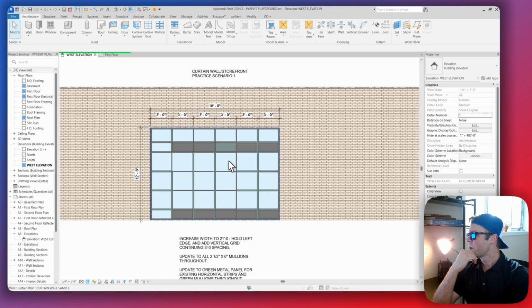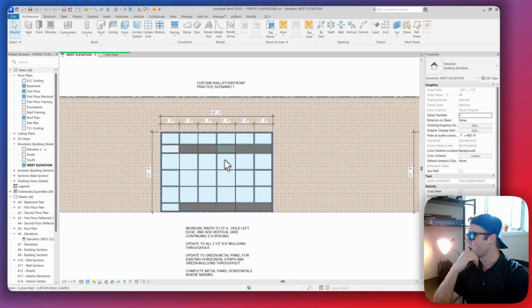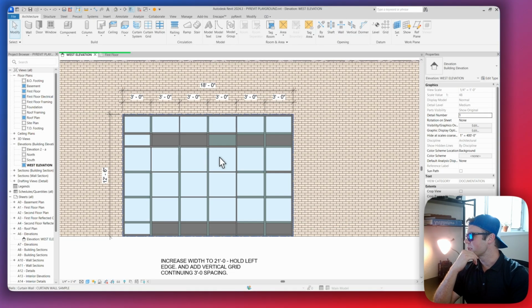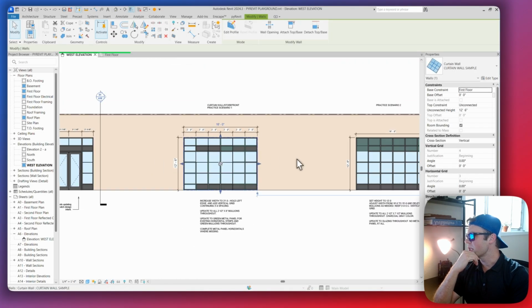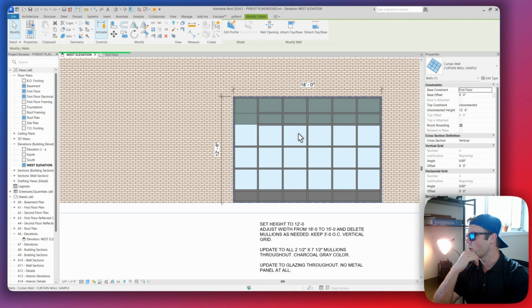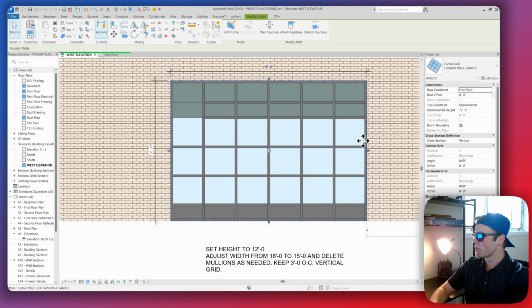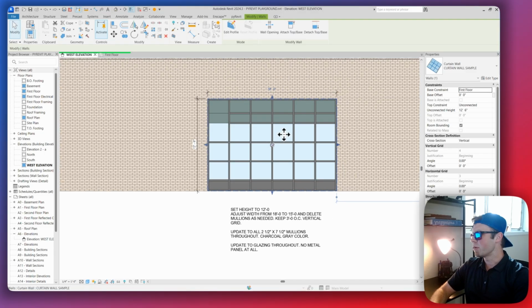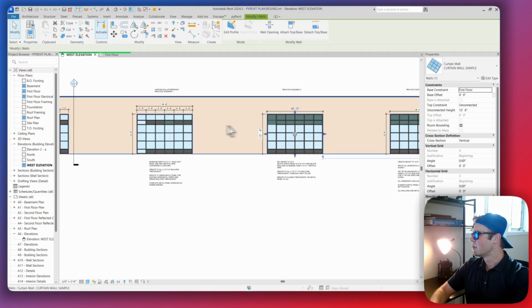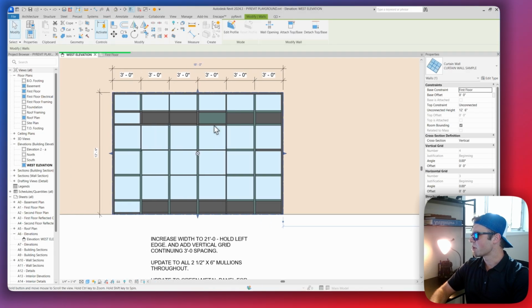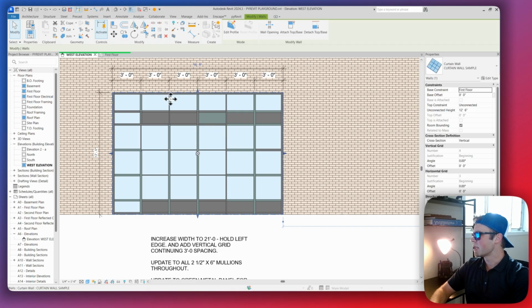I think it helps. And the reason I have it on is to be able to quickly select the extents of the curtain wall with one click instead of tabbing into the edges. Normally you have to tab onto the edge of the curtain wall until you get it right. But with that tool selected, you can just quickly select once in the space within the curtain wall itself, and you should get the extents.